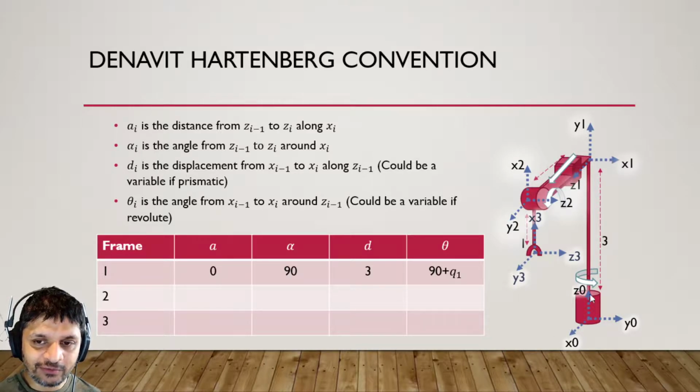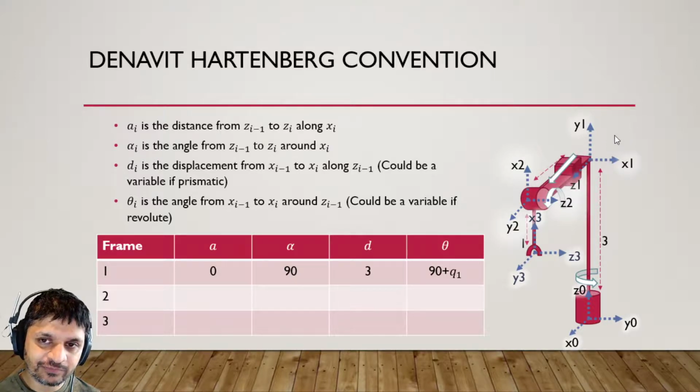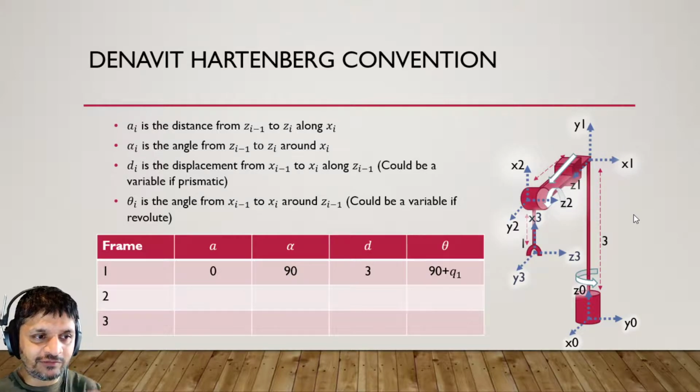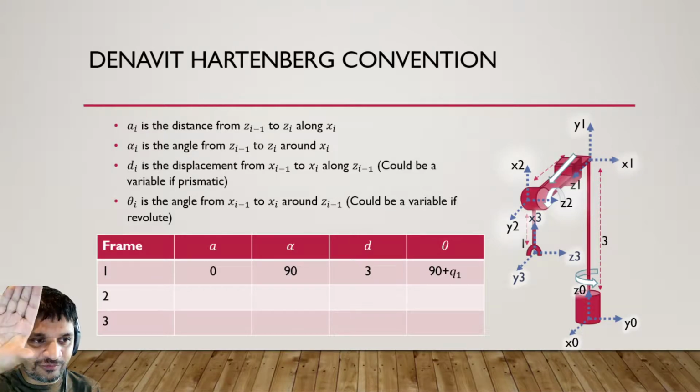But then because we can rotate, when we rotate joint 0, reference frame 0 won't move because it's sort of the world frame, right? It's where the axis is defined. But x1 will move because if you picture the robot, when you rotate the base, this arm is going to sort of swing, right? And z points along where this arm extends, so that means x is going to end up rotating as well, if that makes sense. So basically if you've got this axis,